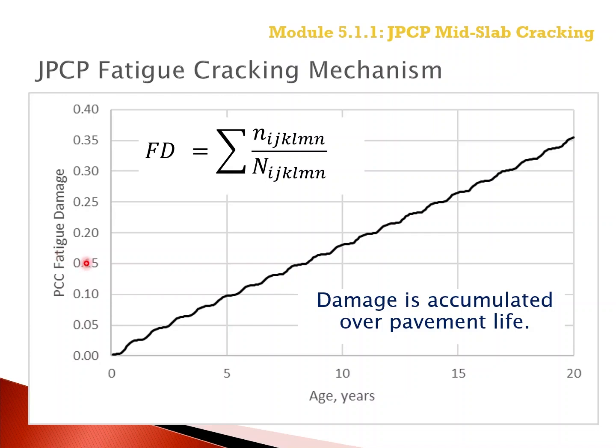So this damage is accumulated throughout the design life of the pavement, and those time-dependent variables or time-dependent fatigue damage of mid-slab cracking are accumulated over time throughout the design period.